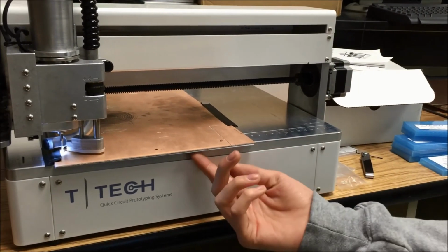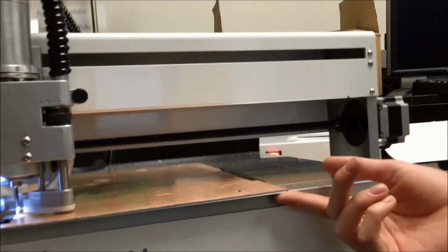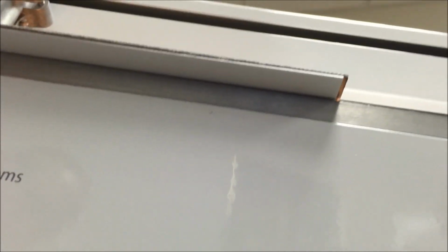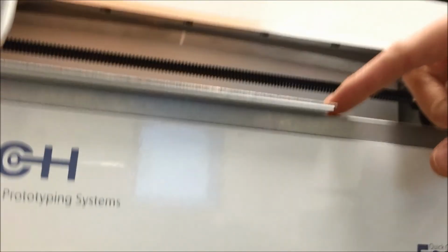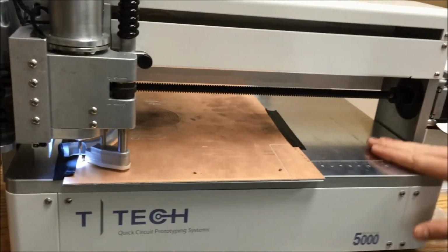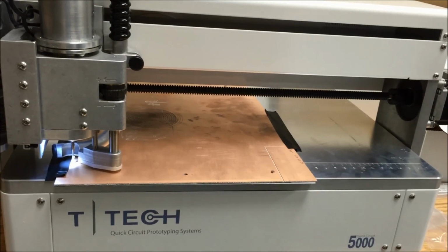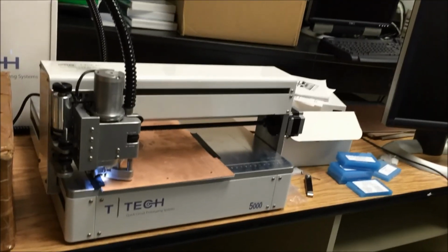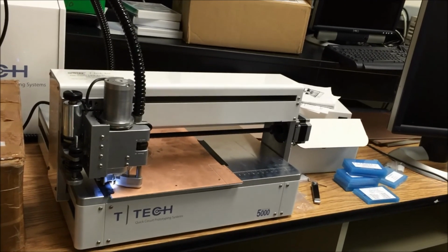And then there's also something worthy of mentioning. There's a layer of poster board material under the board right now. That's probably not ideal, but the reason it's there is to provide a barrier between the bottom layer of copper and the machine's, what's it called, the face itself. Obviously, you don't want to actually run the tooling into the face of the machine, as that's going to cause irreparable damage.